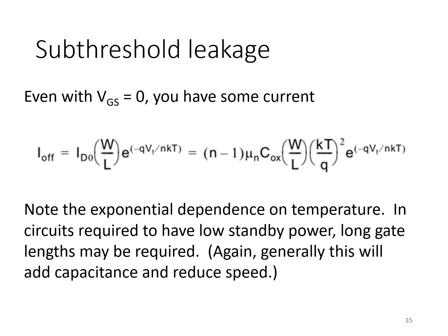In that circumstance, we would expect V effective to be quite negative. So again, because of that exponential relationship, when VGS is 0, we've got to substitute in V effective equals negative VT. And so even though V effective is negative, you get a finite current. This is really when we most expect the transistor to be completely off, and yet we still have a finite current.